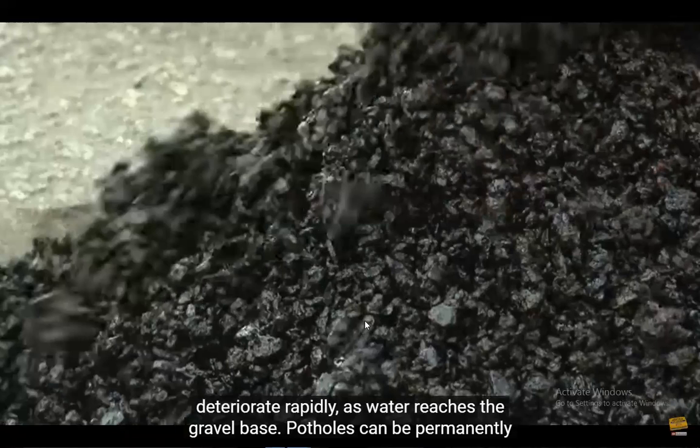High-performance blacktop repair is an advanced all-season formula that permanently bonds to the surrounding asphalt, sealing water out while providing a new driving surface. It requires little surface preparation to be effective. Simply square the pothole edges as much as possible and pour the repair material into the hole. Overfill the hole about 2 to 3 inches above.